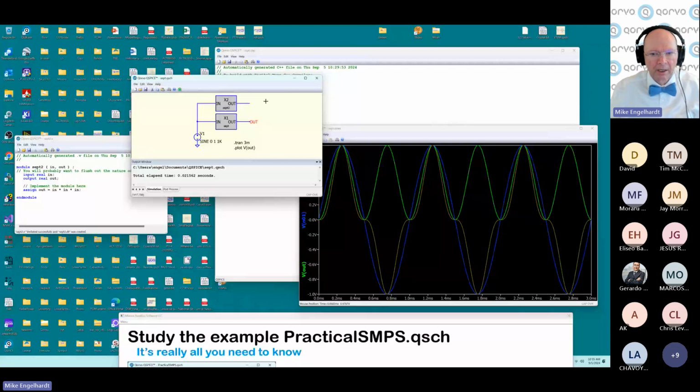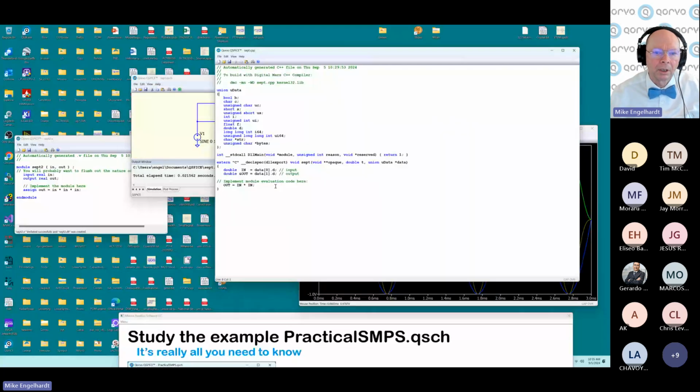boxes I didn't check. Now, the first thing I want to point out is that in this code, you get this function where you just say how you want the output pins to depend on the input. Yeah, but that's not actually useful, because if you just wanted to do that, you could just write a B source. Sure, the B source wouldn't run as fast, but this thing doesn't have any states. You can't make a flip-flop with this because there's no stored memory.